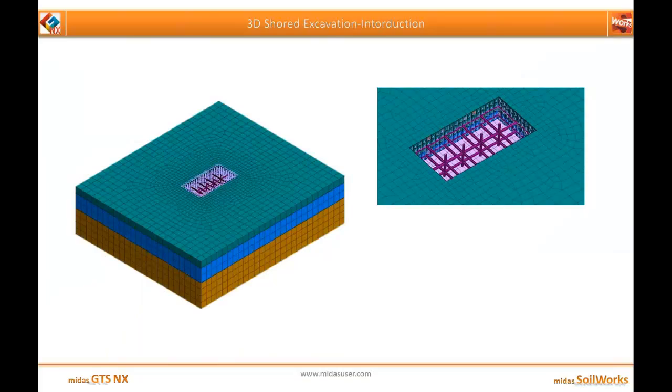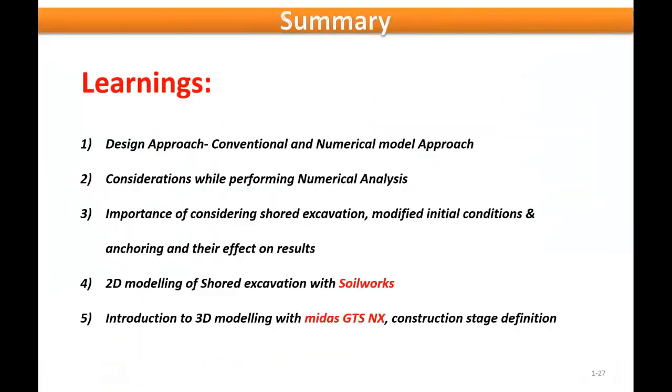So moving on to the presentation, I would finally summarize what we have learned today. So we have learned the design approach, the conventional and numerical model approaches, the differences, what are the various considerations one needs to consider while performing the numerical analysis, the importance of considering shored excavation, modified initial condition and anchoring, and we have seen their effects on results, how much they would have affected our results for the demonstrated model. And fourthly, we have the 2D modeling of shored excavation with Soilworks and a brief introduction to the 3D modeling with MIDAS GTS NX and the construction stage definition consideration.